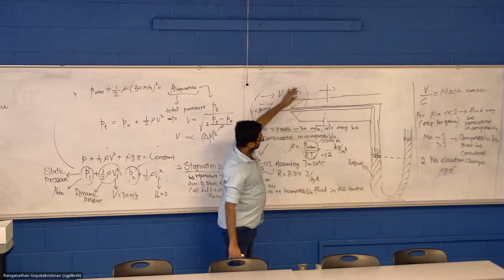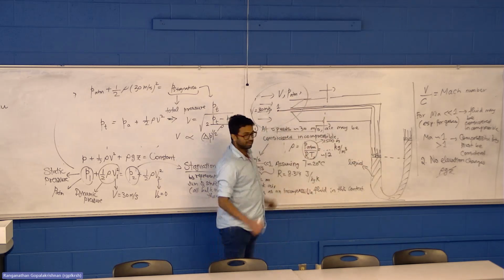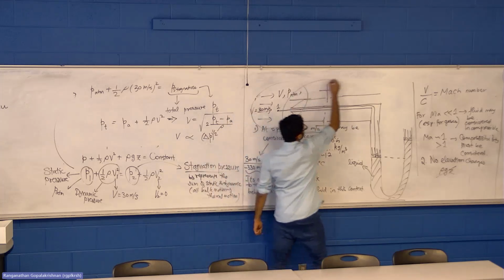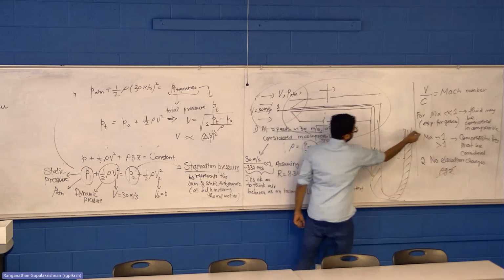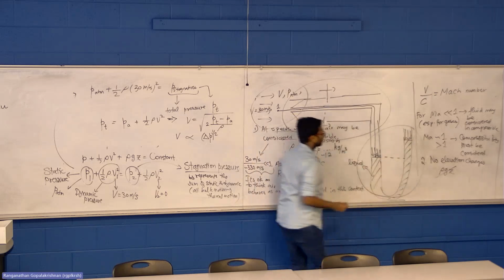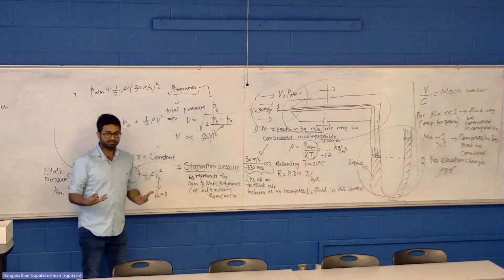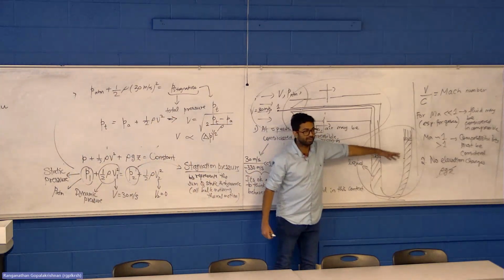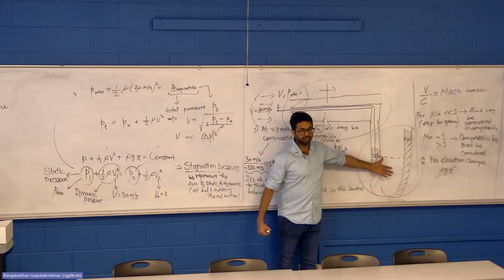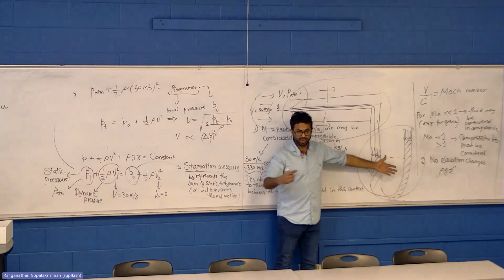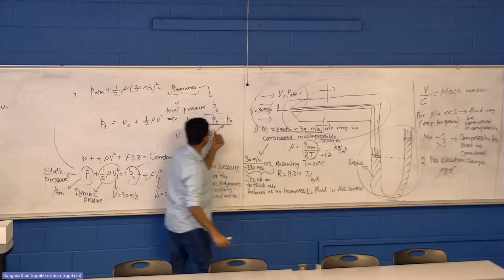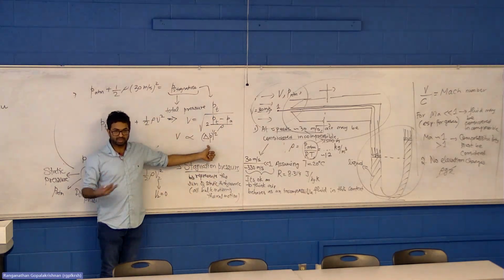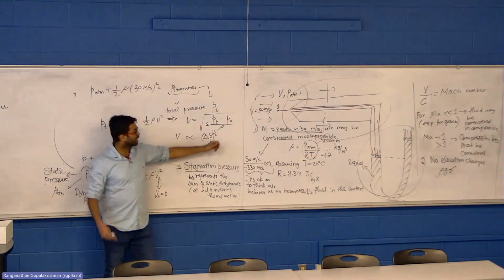Because this system has two subsystems. Do you recognize that? This part creates the pressure difference and this part senses or measures the pressure difference. Do you see that? You can swap this out. You don't have to have a liquid based manometer. You can stick a pressure transducer here. It would read out pressure difference. At the end of the day, you need pressure difference. You don't care how it is measured. Is that clicking? So there are two systems here.